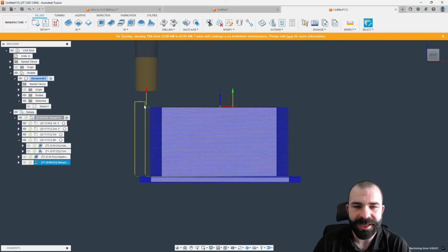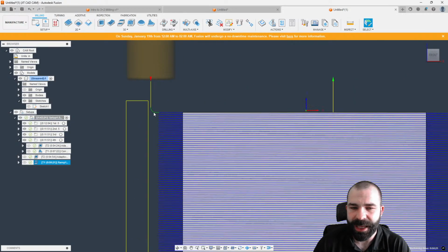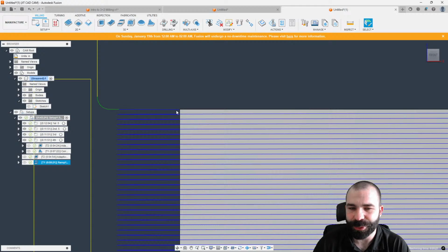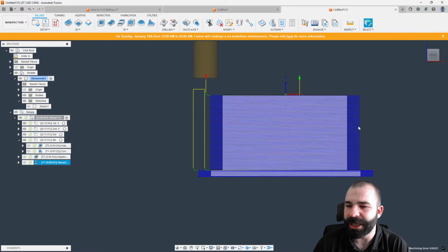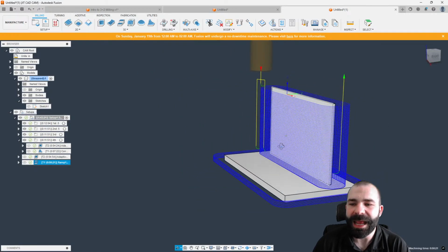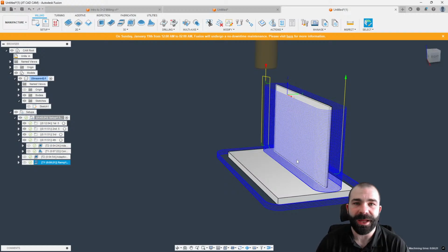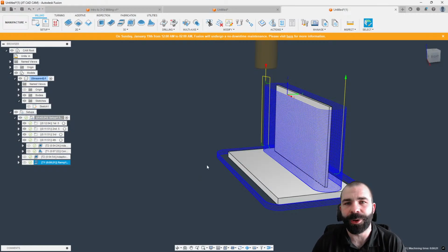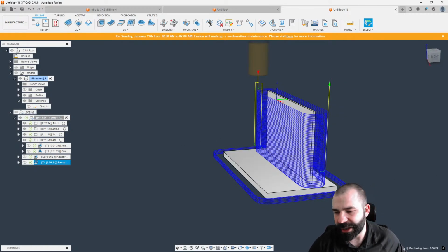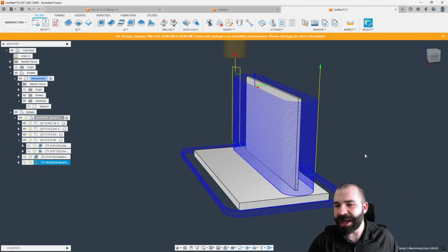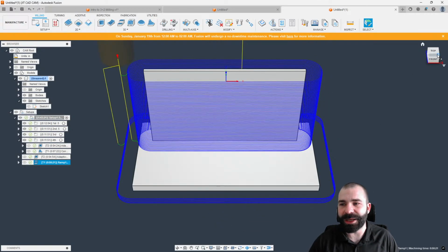So as you can see here, I actually enter my part up top. And if you pay attention to that very first blue line, we're going to run all the way down. And again, we're going down in 40 thou increments, and we're basically 3D'ing down this part. So if I traditionally rough this out and left like 30 on the walls, and that's more than stable enough, I could come back with ramp. And then as I work my way down, we should be able to prevent quite a bit of deflection, right? Or chatter in that. So hopefully, Ash, that answers your question. Anybody else have any questions outside of that?